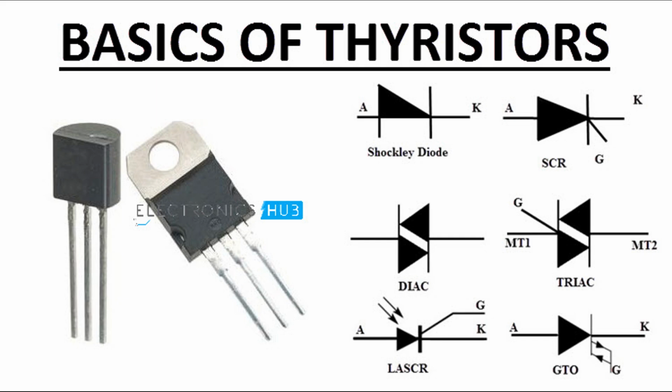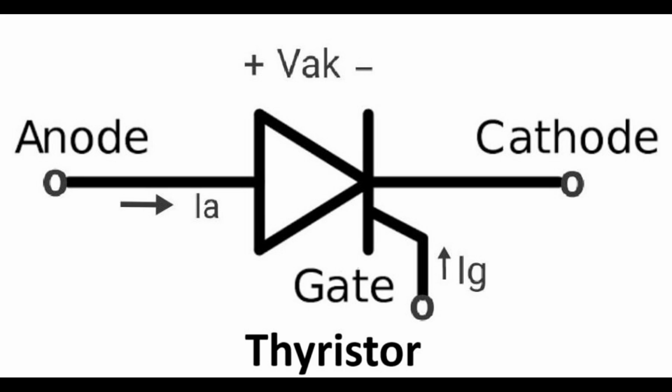Commonly used in circuits to provide a consistent and symmetrical trigger signal for triacs in AC applications. Phase control, used in light dimmers, fan speed controllers, and other phase control applications to control the phase angle of the AC supply. Overvoltage protection, can be used to protect circuits by clamping overvoltage transients.